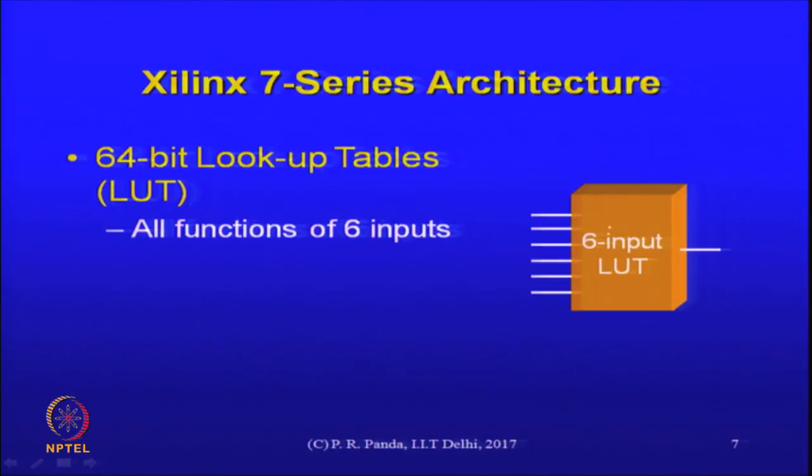While that is the basic idea, of course, people are always working on tweaking and improving that lookup table structure and that CLB structure. So, there are a few other things that are useful, and the FPGA designer would make those things also be part of the CLB structure. We said that there is a need for storing data. That storing data does not actually form part of the CLB. You would have to store data in block RAMs if you wanted to do that, but there are some flip flops that they would include in addition to these LUT structures that are used for combinational logic only.